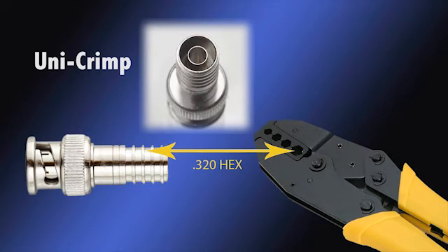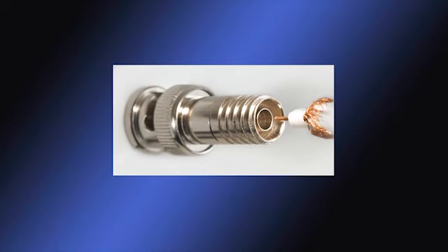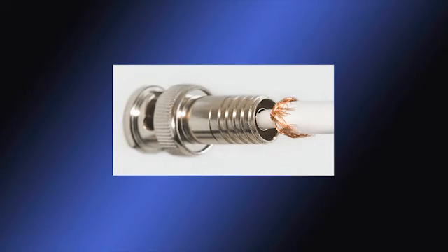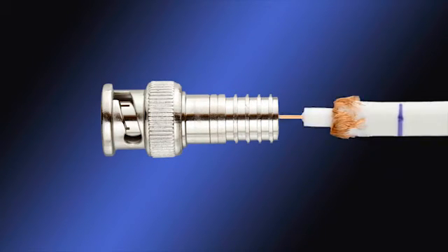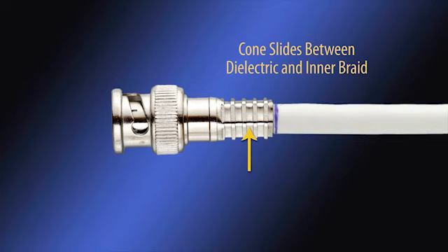Most importantly, this internal design provides for the connector hex to crimp down on 2 braids and the outer jacket of the cable. This is accomplished by folding the braid back after stripping the cable properly and inserting the cable dielectric into the inner cone structure of the connector. The internal construction now has the cone, the inner braid, the cable jacket, and the braid that was folded back. This is what the hex crimps down on and provides a very substantial structure to crimp down on to.